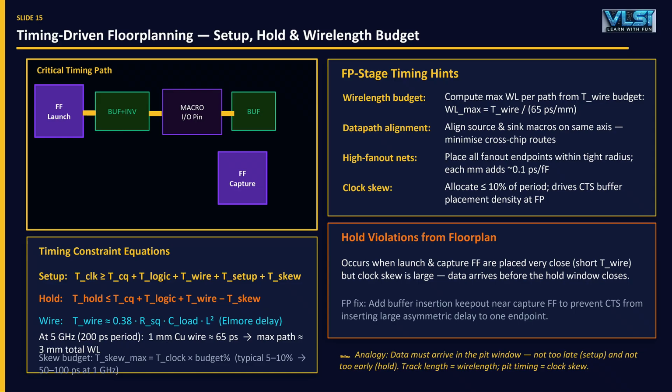Timing. Imagine catching a train. If you arrive late, you miss it. That's setup violation. If you arrive too early and the system is not ready, that's hold violation. In chips, signals must arrive within a precise window, not too late, not too early.